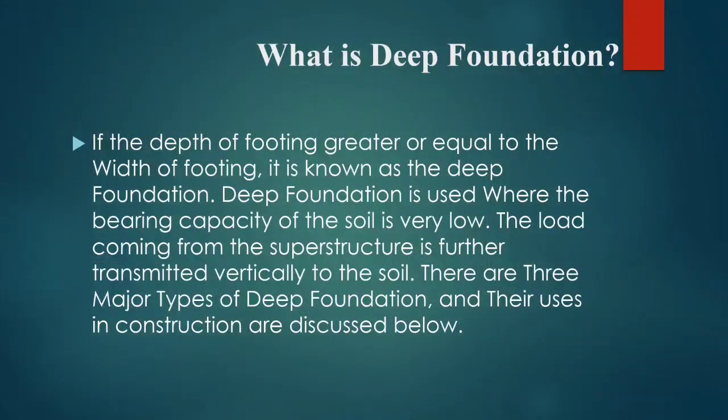So, first, what is deep foundation? If the depth of footing is greater than or equal to the width of footing, it is known as a deep foundation. Deep foundation is used where the bearing capacity of the soil is very low. The load coming from the superstructure is further transmitted vertically to the soil. There are three major types of deep foundation, and their uses in construction are discussed below.